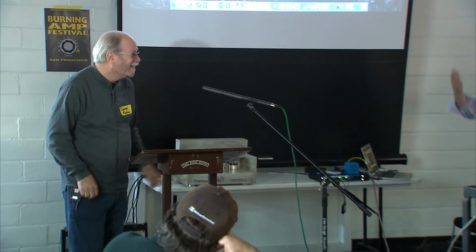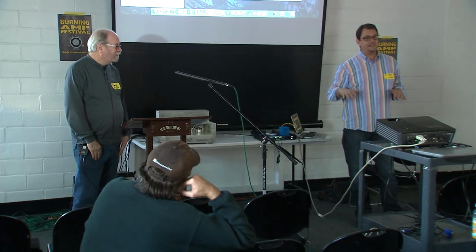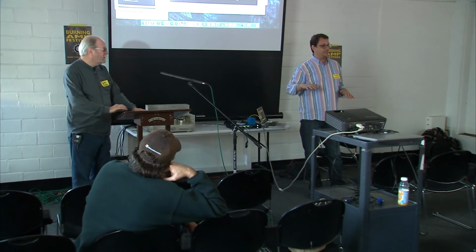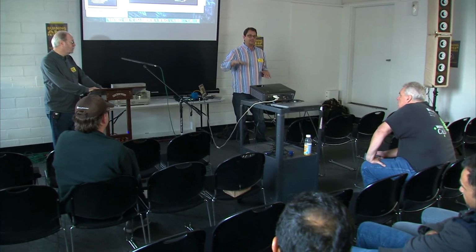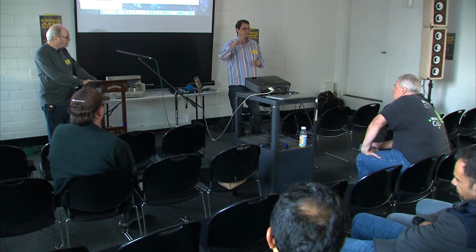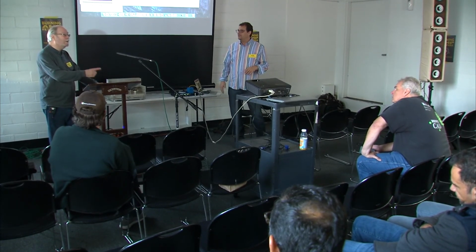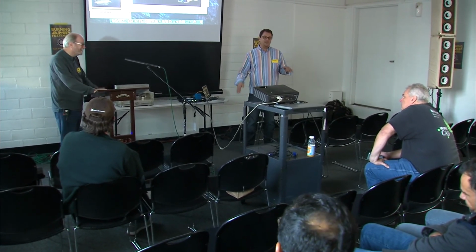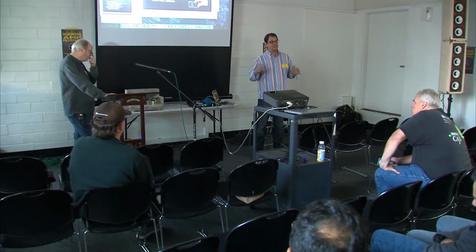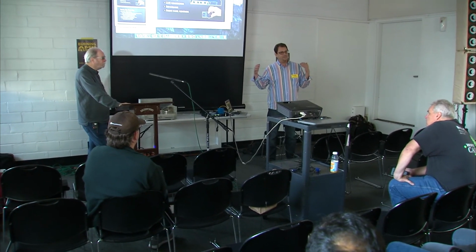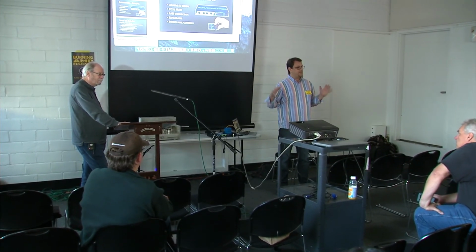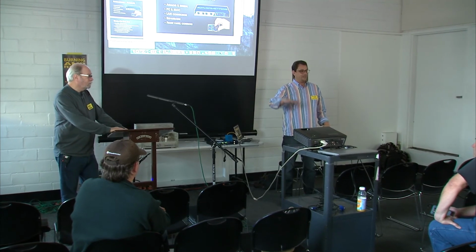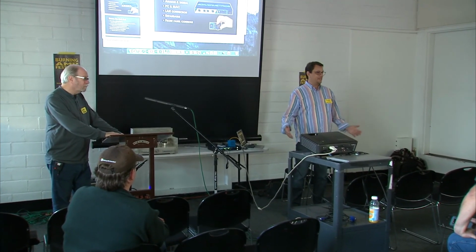The other thing about noise is that there's steady noise, which your ear actually filters out pretty well. You can be in a room with the hum of a fan, and you don't hear it for a while. But there are devices that pump noise, where the noise level actually changes. It could be because of a DSP algorithm. Sometimes it's the converters themselves: the noise floor changes as they change between voltage levels. Or you have a fan that changes speed constantly. You hear that. So understanding how noise impacts your enjoyment: you can listen to some very old recordings that are fairly noisy and still say, wow, that's an amazing recording, because that noise is steady throughout. But if that noise keeps changing, you're going to say, oh, that's terrible, because you're going to notice it.